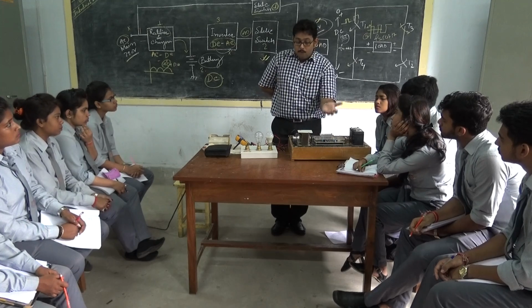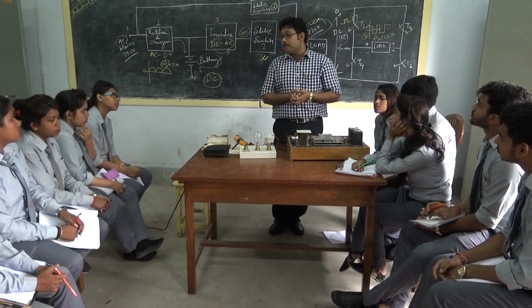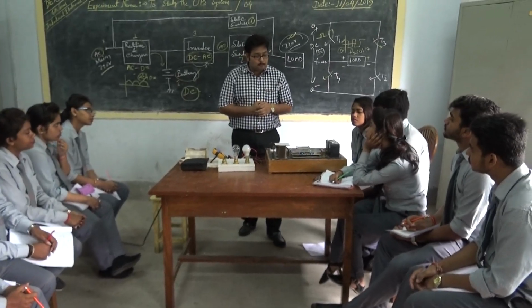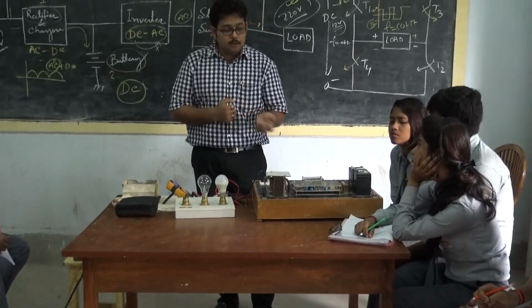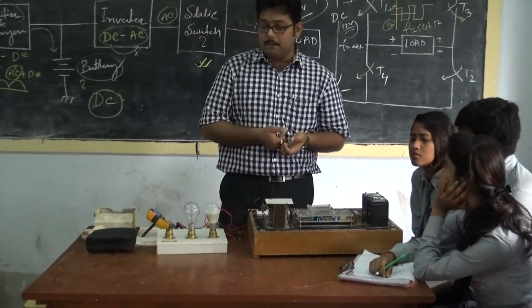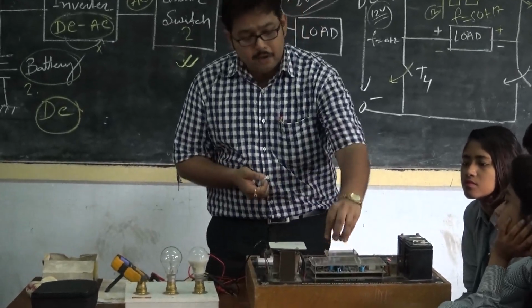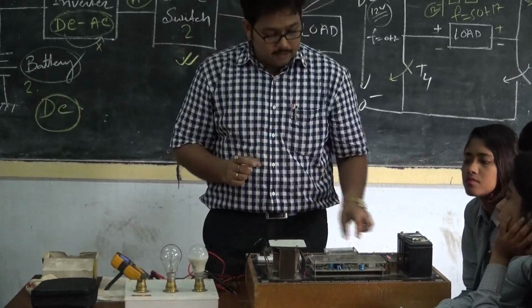If this kind of fault happens, then you will not be able to get the information that the main supply is not available. It is harmful, because if you are doing some work on the PC and you don't know that the main supply is not available, your work may be lost. For this purpose, if the buzzer does not work, open the circuit and change the buzzer.